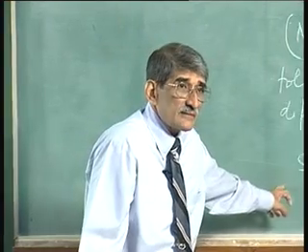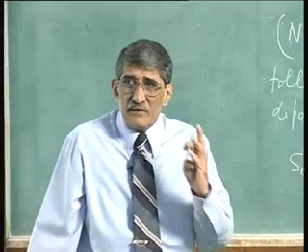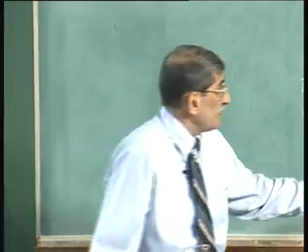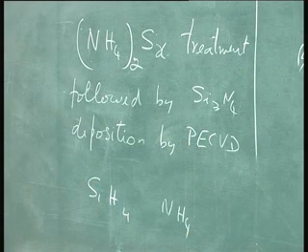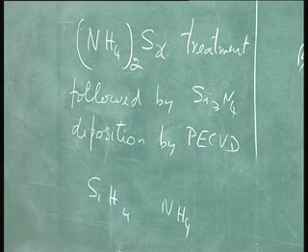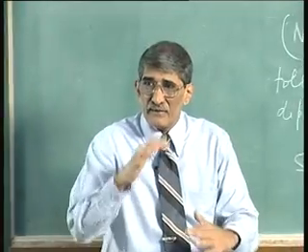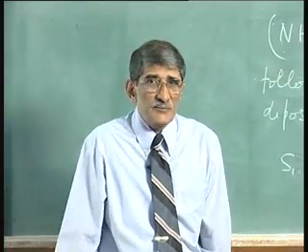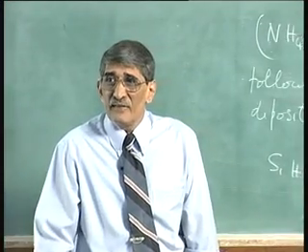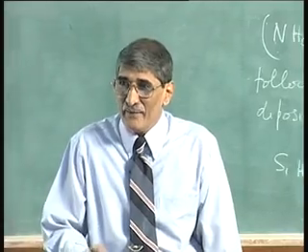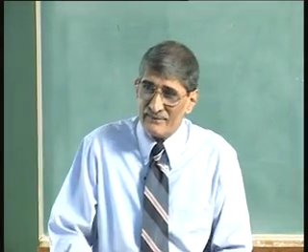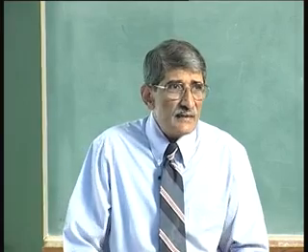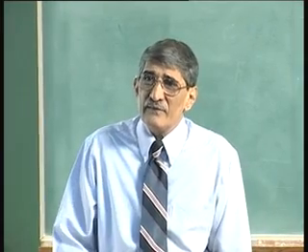When you make devices with this, the way you test it is use this PECVD nitride as the gate dielectric, take gallium arsenide layer, passivate it with ammonium sulphide, put nitride, put a metal gate, source drain contacts put, you get instead of MOSFET you got MISFET, metal insulator field effect transistor. You call it insulator because it is not the oxide. So, it can be anything, nitride, when you put it you get excellent field effect transistors.